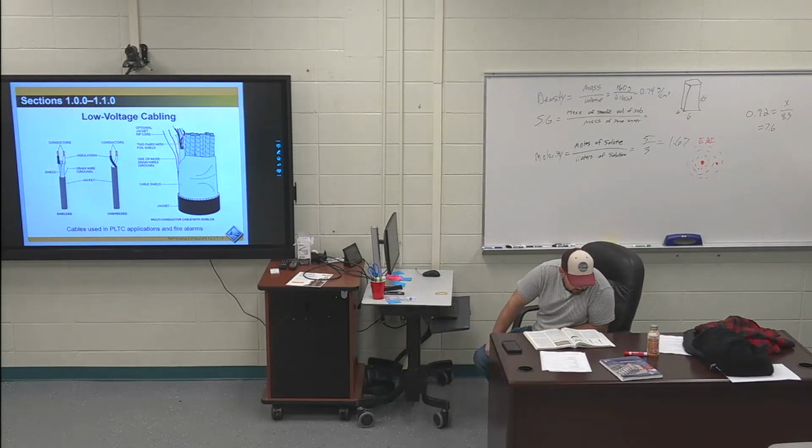Top right. So I gave you all the top left, the last sentence: to be effective, the shielding drain wires must be grounded. Gave you all that one. Something to note on grounding drain wires, you ground a drain wire only on one side, not both sides.